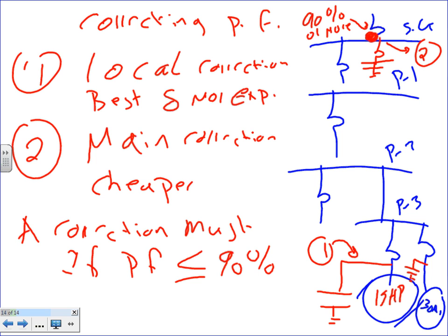Without getting into too much detail, they allow you, when you start the chiller or major motors, to go down a little bit. But on average, when you're running fully and everything is right, for a certain amount of time they want your power factor maintained at 90 and higher, not less than 90. Any question, guys? And look where they measure it. The utilities care about this. You care about inside your building.